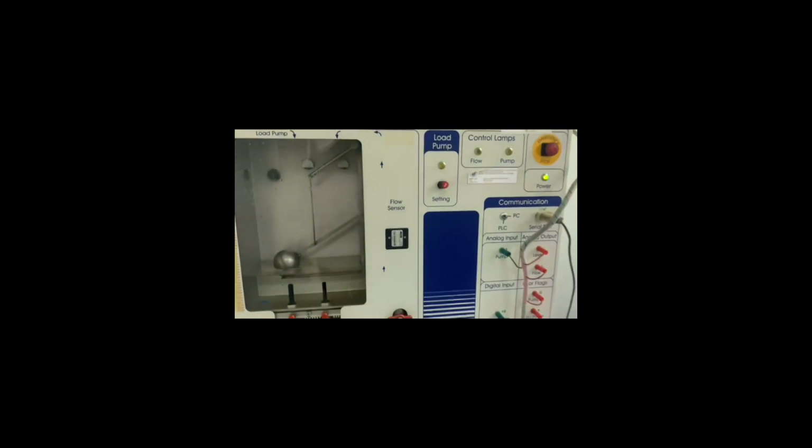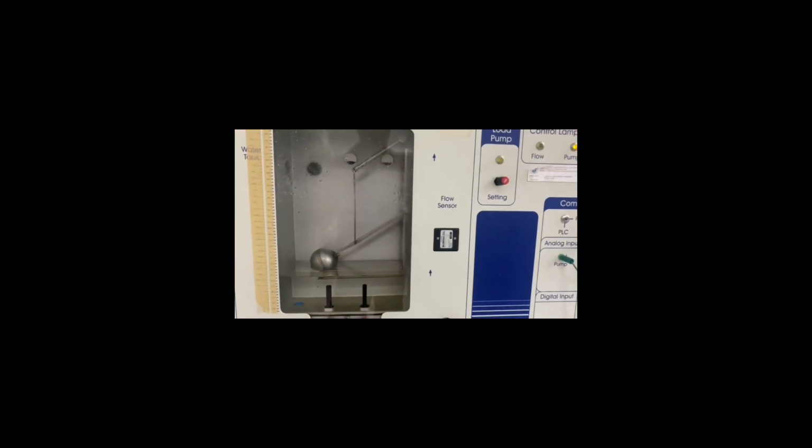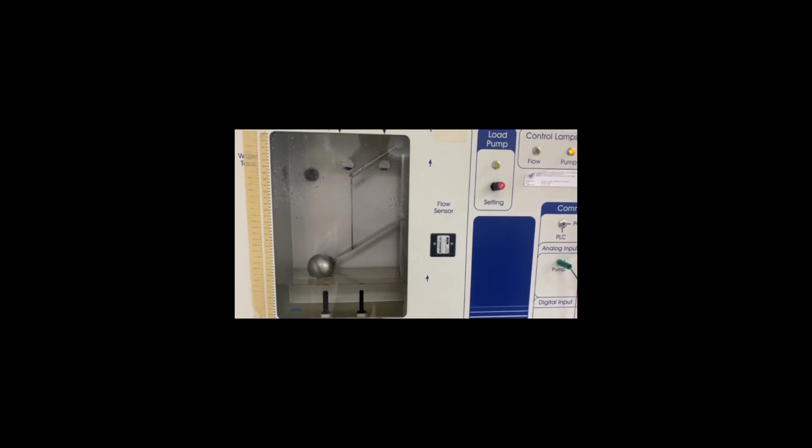Then click run and run the system until it reaches steady state. After a while, record the system output H and the controller output M in the table. For the fifth task, at 108 set point, change the KC value in the dialog box to 1 and click run and run the system until it reaches steady state.